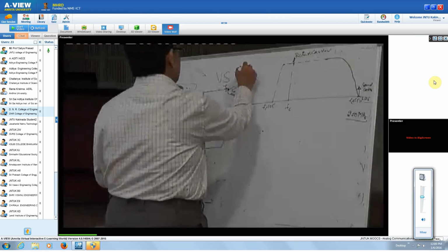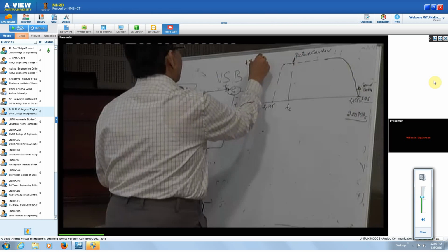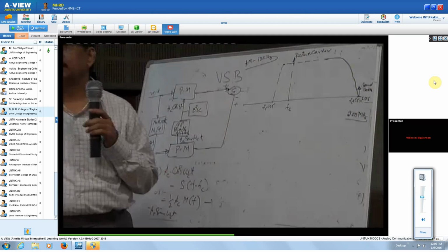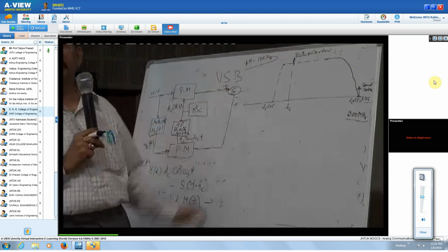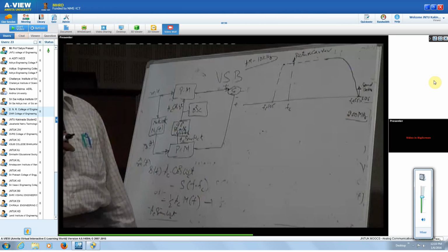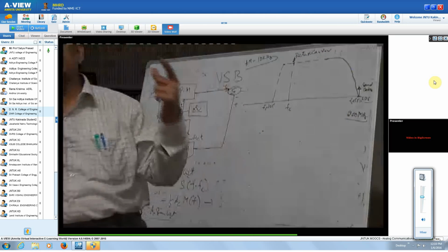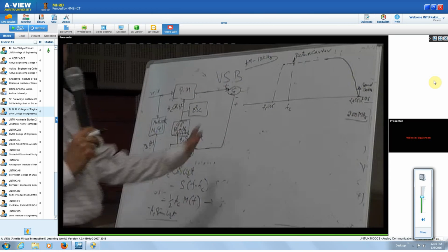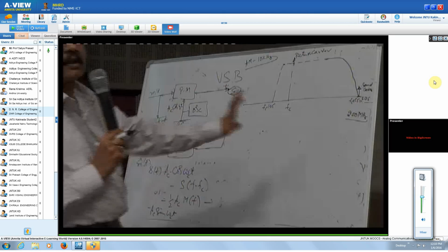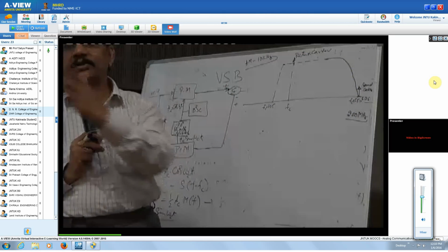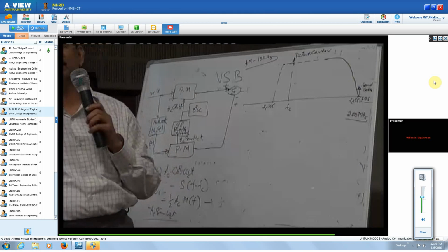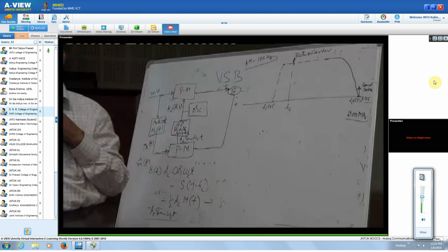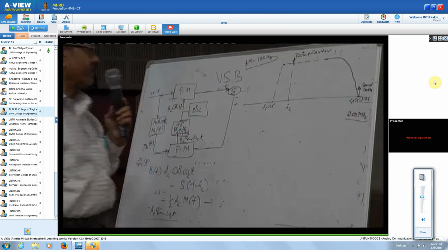For the AM transmission, the bandwidth that we require for each station is going to be 10 kilohertz. AM broadcasting, we require 10 kilohertz. Whereas for FM, each station bandwidth, we fix it as 200 kilohertz along with the guard band and so on. The total band, we are going to have it divided into each of these 200 kilohertz band pass signals. Anyhow, we will see that when we are talking about FM modulators and transmitters.